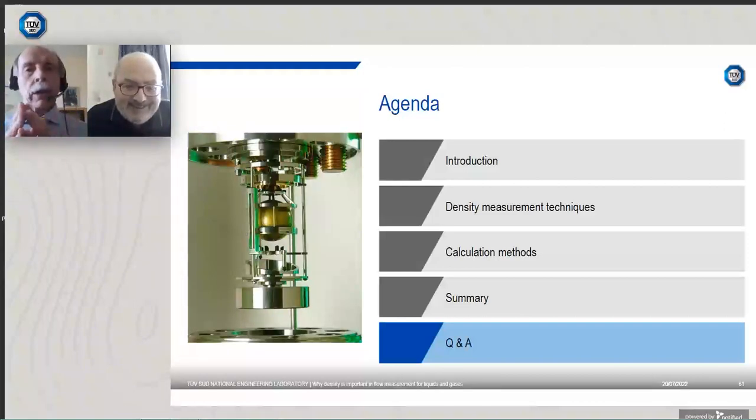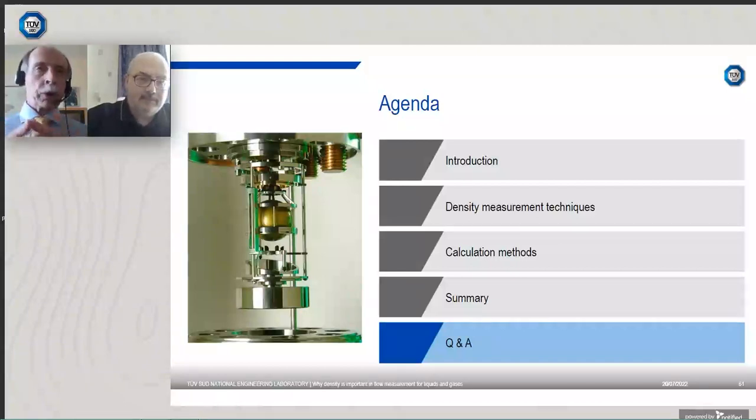It's largely mathematical and it's physical. Part of the reason is that equations of state are typically written in terms of reduced variables: reduced temperature, reduced pressure, reduced density. And the reducing parameters are normally the critical properties. So critical temperature, critical pressure, critical density.